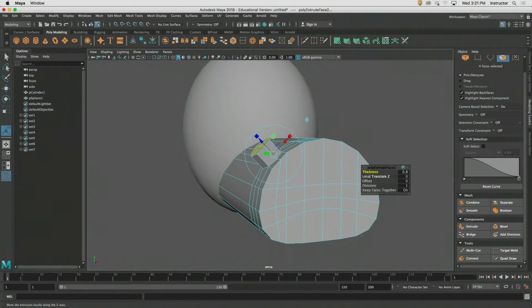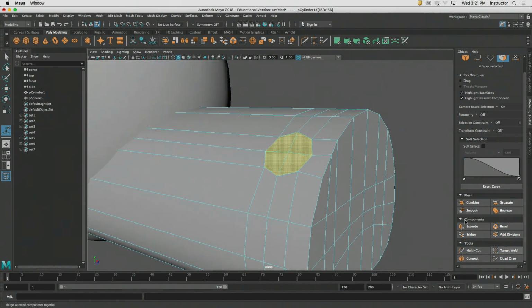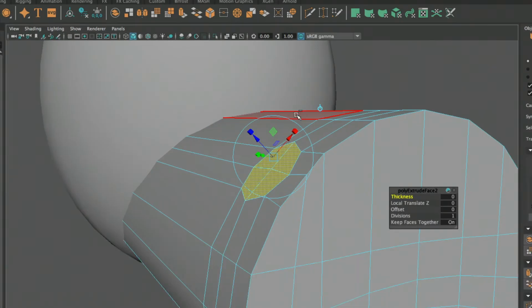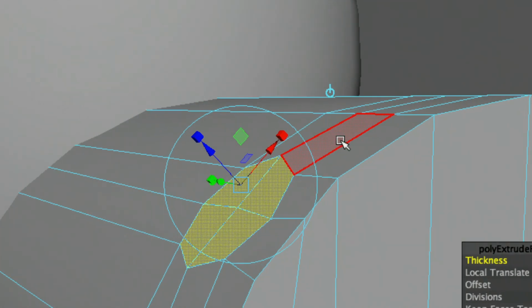Cool, huh? Now, one kind of change, and I want to show you this. You'll see this in a couple different spaces. So I did an extrude, okay? Now, look what direction my tool handles are showing up on the mesh itself, okay? The tool handles are following the surface normal.